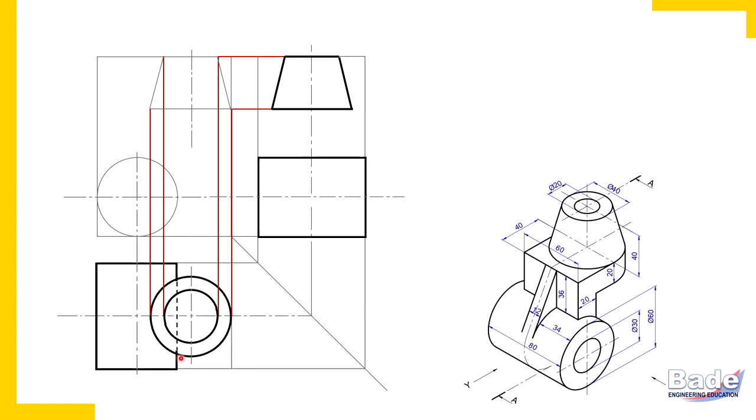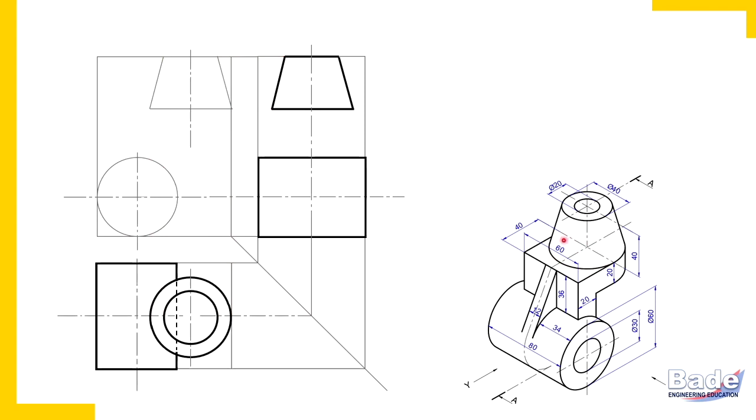Okay. So now let's proceed for this horizontal U-shaped pleat. Check here this U-shaped pleat. This curved edge of this pleat is coinciding with the base of the cylinder. Now focus here where right now red dot on your screen is. Check here, I have drawn that base circle. Okay. So this is that U-shaped pleat. So its U-shape appears in the top view, and in front view and side view it should appear a rectangular strip. After all, it is simple U-shaped pleat.